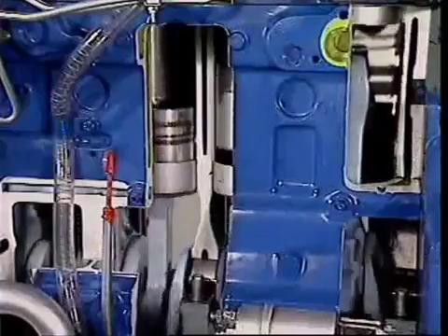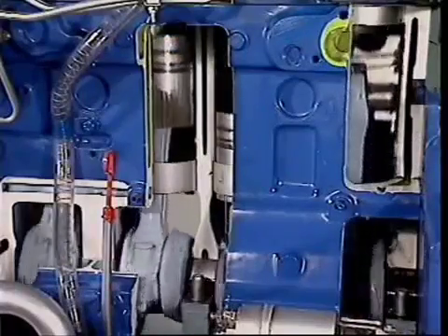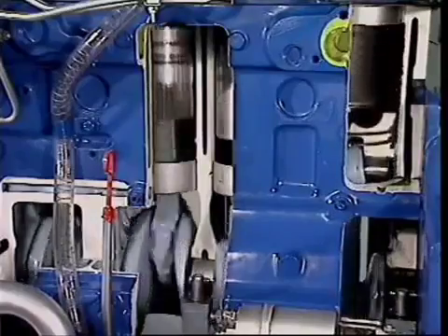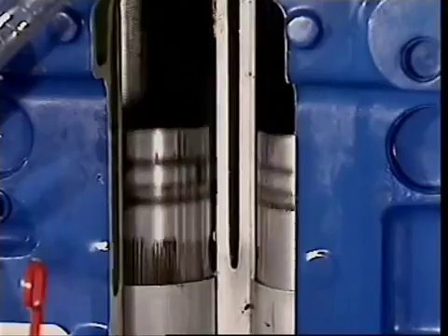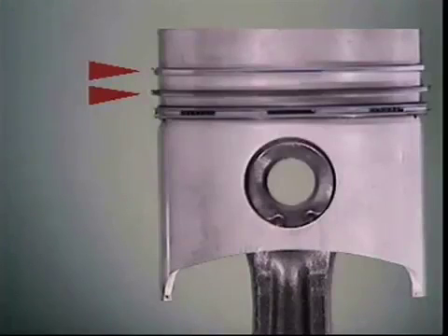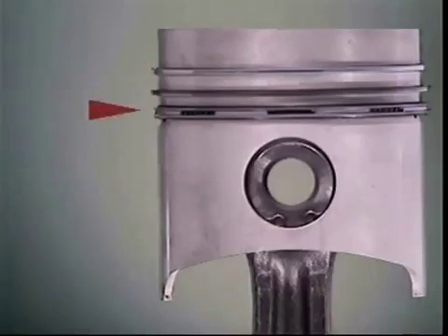When the piston is fitted, there must not be too much clearance. It has to seal in the high pressures and temperatures generated by combustion. This is done by piston rings, held in grooves in the side of the piston. The top 2 rings are compression rings. The lower ring is an oil control ring. It scrapes excess oil off the lower cylinder walls.